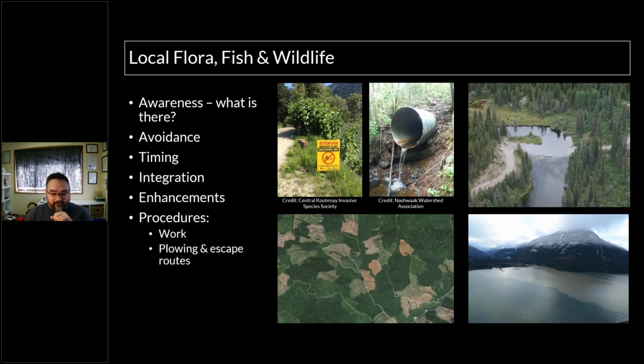What I find is overlooked a lot of times when you're crossing a stream is understanding exactly where the corners of your bridge or the ends of your fill on a culvert are going to be, and what those stream banks are looking like. If you're trying to figure out how big a bridge needs to be, even on a temporary road, you have to look at the stream bank.